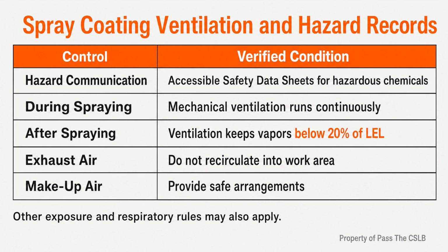At delivery, compare the physical container with that register. During work, make the substitution rule clear to every foreman. No replacement paint, adhesive, sealant, or aerosol goes into use until its compliance path and documentation are reviewed. Before the enforcement visit, audit the records against the containers that are available for field verification and confirm any stricter local requirement with the enforcing agency.